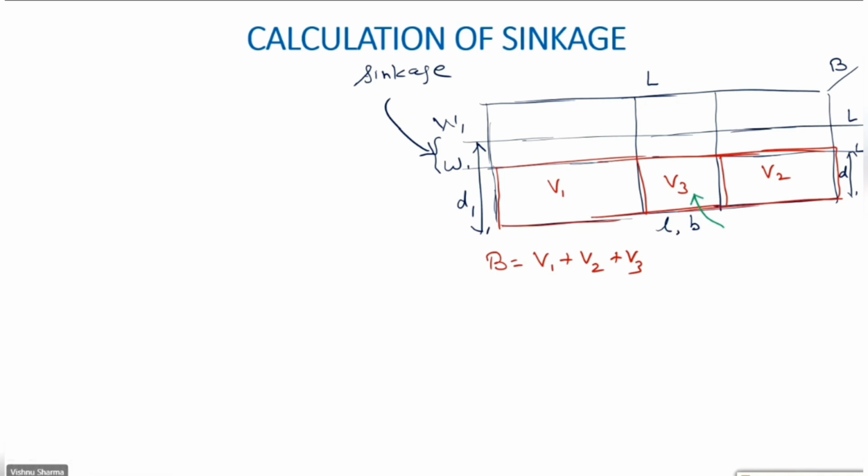When this midship compartment is bilged, sea water gets into this compartment, and it is free to come out also. So now look at the diagram, and please use the notations that I have marked. Use capital L, small l, so specify which notation you are talking about. Look at the diagram and tell me what is the buoyancy that was earlier being used and now lost.